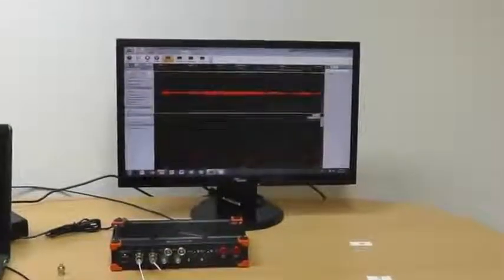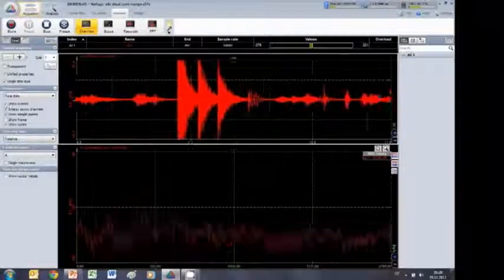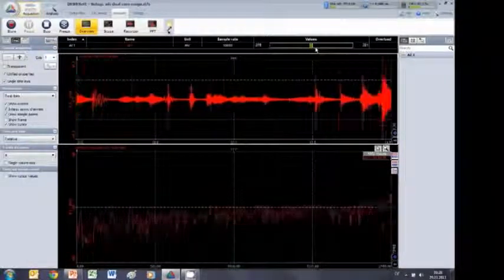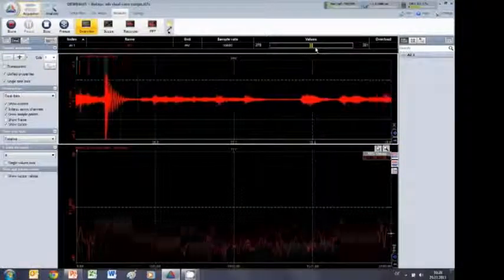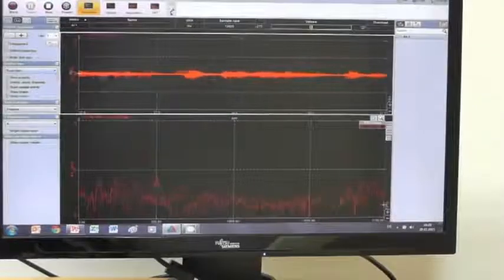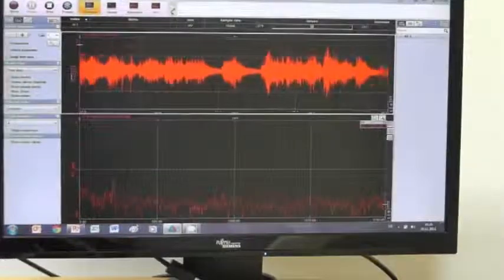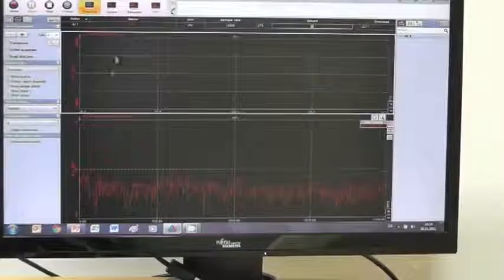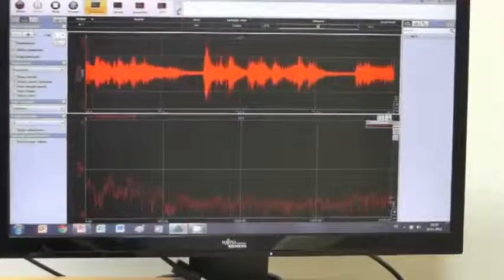So here we see the recorder signal, and you can see already my voice is recorded. Here on top we can see the dynamic range, and when you look at the small detail of how much we really record, on the scaling you could see maybe this is 10 millivolts plus minus. If I go to full range, you see this is 10,000 millivolt full range. So how about now? We don't see anything, but if I just make auto scale, you can see the small tiny signal coming from this sensor.